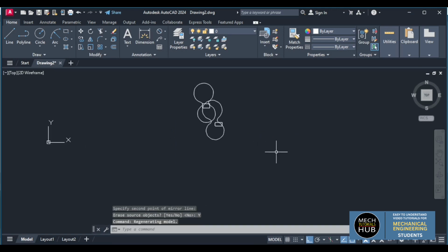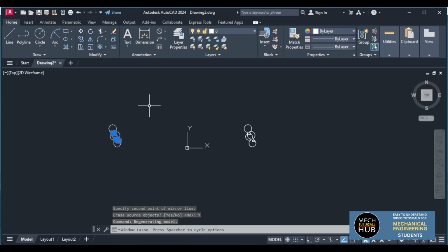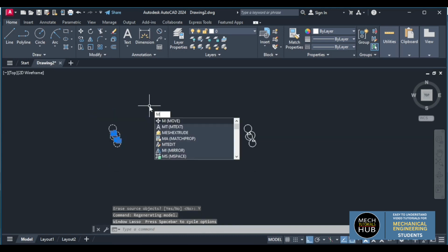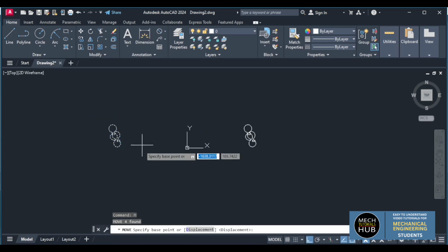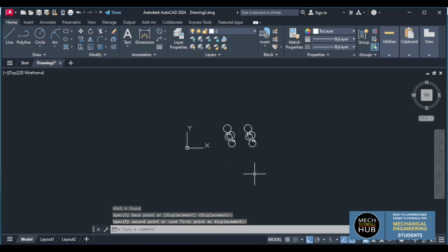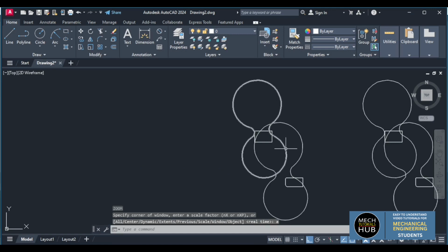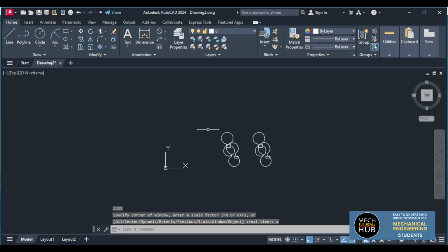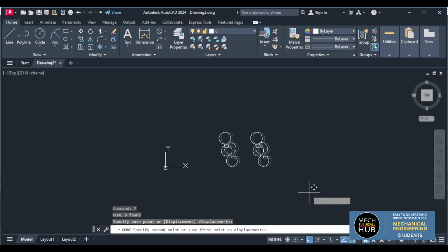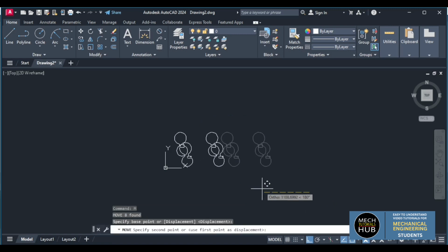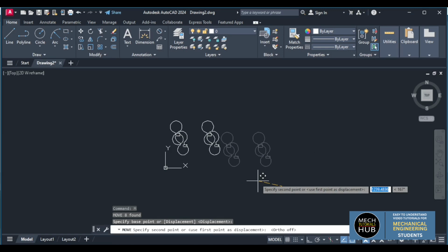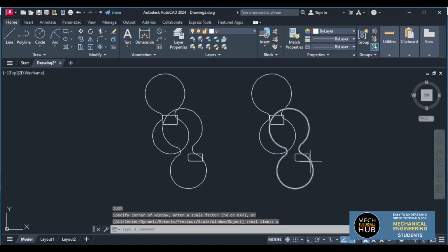Have a look. Okay, now I want to take this near the existing sketch. M, enter, to move near this one. I'll say Z, enter, A, enter to fit it to the screen. Now I want to bring these two near the coordinate system. M, enter, near the coordinate system. Now I'll turn off F8 so I can place it wherever I want. Z, enter, A, enter will help you fit it to the screen. This is how the sketch will be.